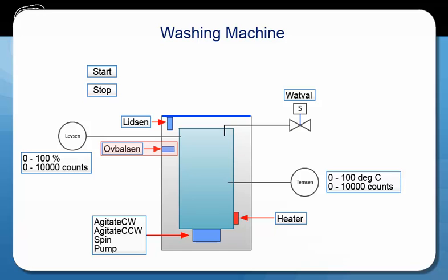It has an overbalance sensor that will operate if the machine overbalances, and the PLC program will have to latch. It will pause the operation. Lifting the lid and closing the lid will reset the overbalance, and the machine will continue the cycle. If the lid is lifted, then the operation will pause whilst the lid is up and continue when the lid is closed. The PLC will control solenoids that operate the functions of the machines.